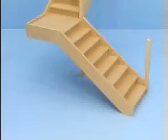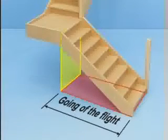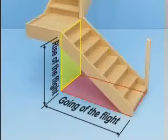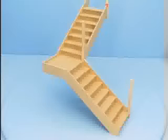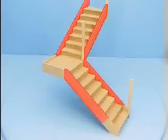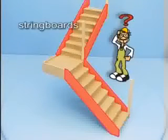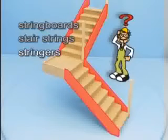The total horizontal distance covered by the flight is known as the going of the flight. The total vertical distance of the flight is called the rise of the flight. Inclined boards running from the top to the bottom of each flight support the treads. These boards are known as string boards, stair strings, or more commonly, stringers or simply strings.